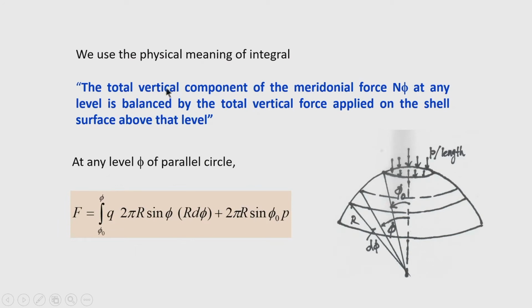So, we use the physical meaning of the integral. The physical meaning of the integral says that the total vertical component of the meridional force n phi at any level is balanced by the total vertical force applied on the shell surface above that level.